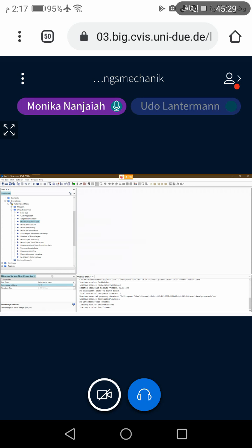But I see here it's 3 times. You said by a factor of 2. Yes, it's 2 to the power of 3, which means 3 times refinement. Each refinement level is a factor of 2, but compared to the base size, it will be a level of 3. So 2 to the power of 3 means 8 cells instead of 1 cell of the base size. So the base size is 1 cell, first refinement is 2 cells, second refinement is 4 cells, and third refinement is 8 cells. Now I get it. Thank you very much.